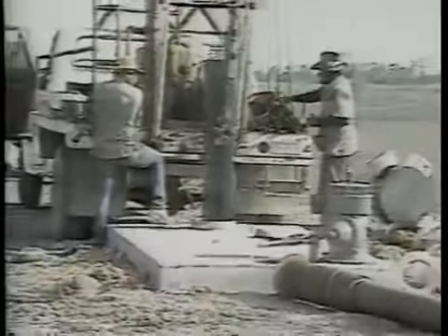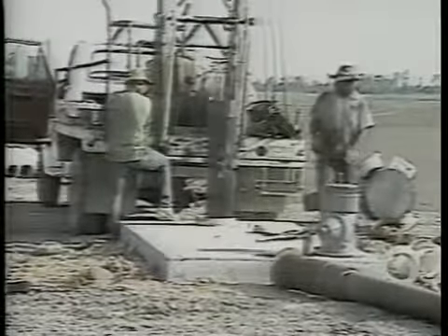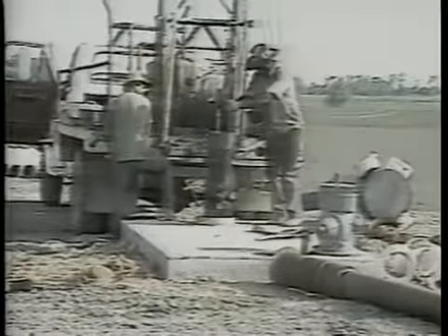The basic composition of compounds in water is determined by the location of its source. For example, well water obtains ions directly from mineral deposits of the aquifer in which it is located. Therefore, water from a limestone aquifer will contain large quantities of calcium and carbonate ions. Surface water will contain ions dissolved from the stream bed and from runoff over land into the stream. In many areas, various types of water may be obtained by drilling at different depths. Three types of fresh groundwater sources are usually present in the south.